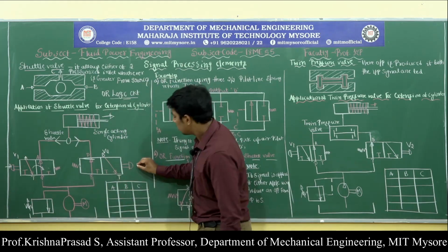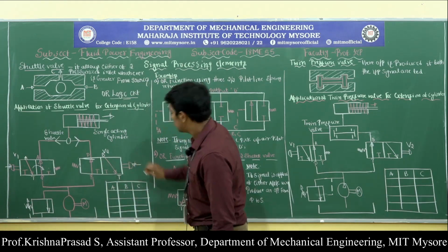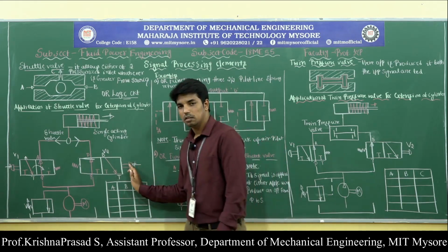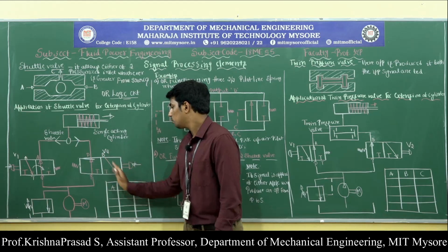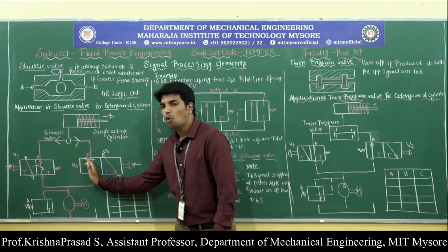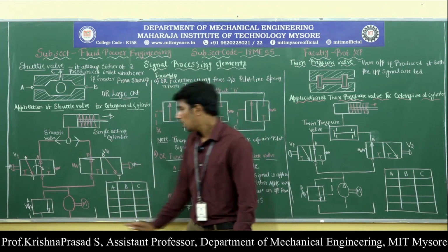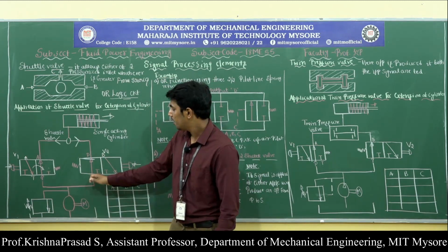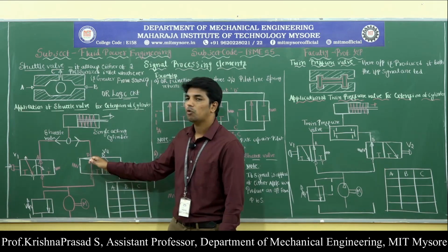Now apply pressure on the push button of valve 2. Now this direction control valve shifts from the normally closed condition to the normally open position. Compressed air will flow from the pump into the inlet port P to the outlet port B.